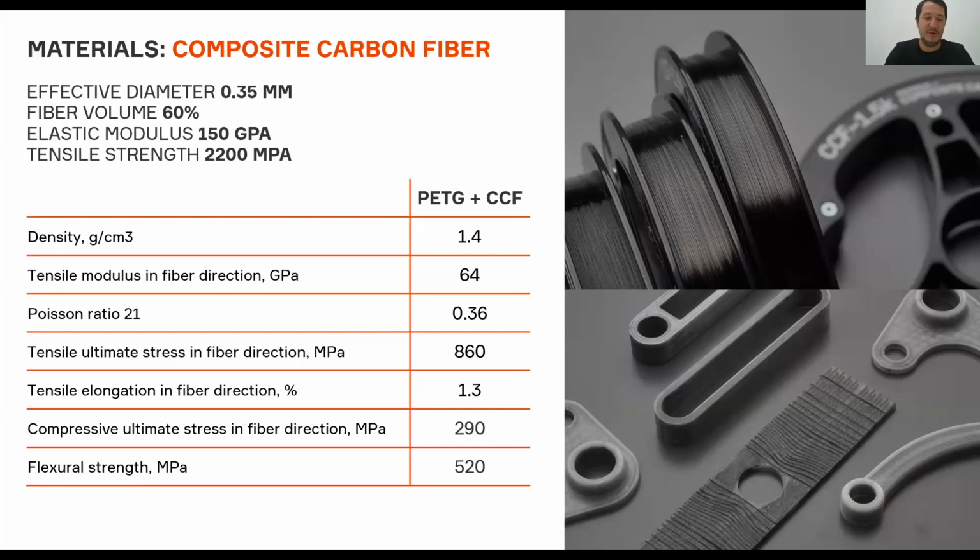With the chopped fiber infused materials, the viscosity is normally much higher, so there is a higher probability of clogging that would lead to the print failure. So that's why we are not currently too much investigating into that topic, but it's definitely interesting, and that's definitely something that you can do and test on your own.